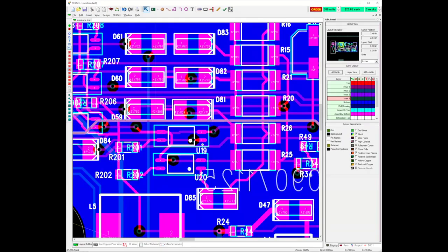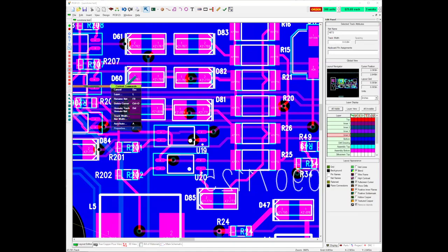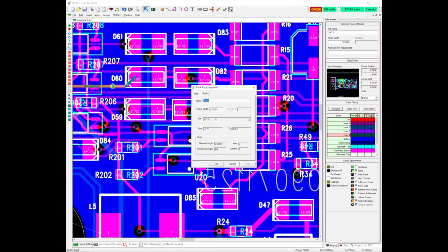Okay. So on my screen, I've got lots of vias. What I don't have is anything that tells me, let's see, properties on that wire. You can basically just select the wire, right mouse properties, and it will tell you what the via that you're using on that wire is. So on this wire, I'm using a trace width of 15 mils is my standard width.